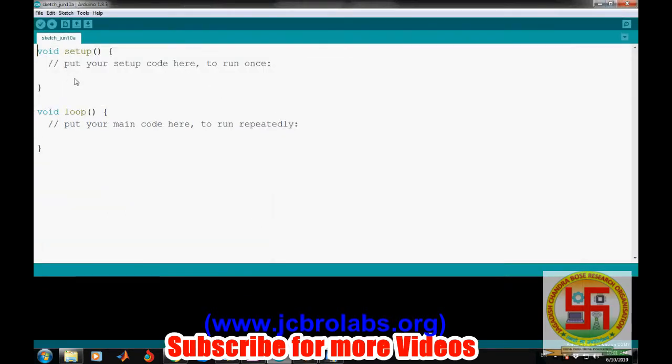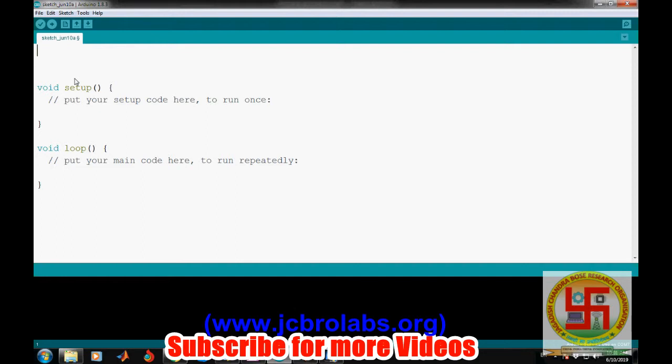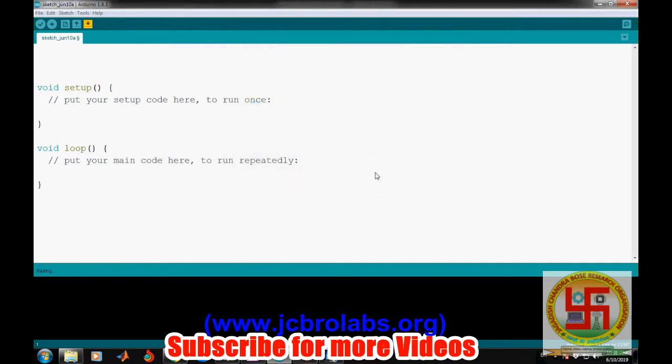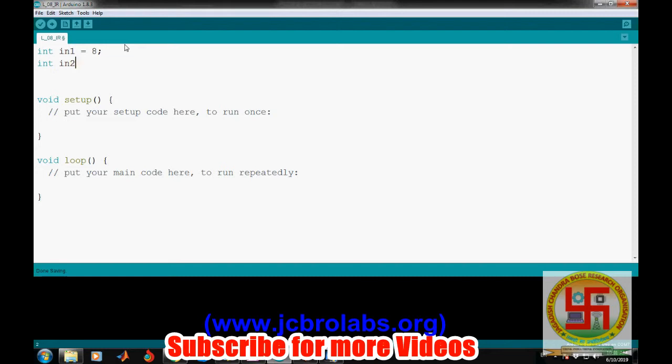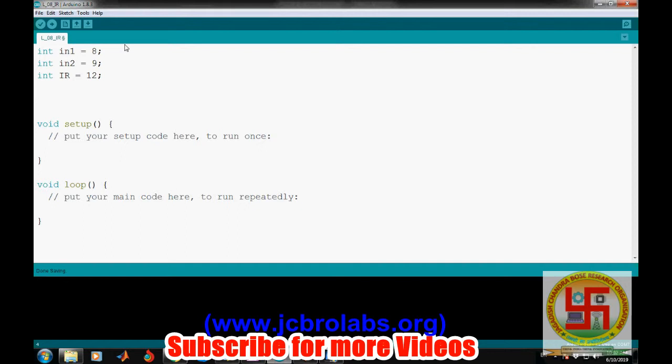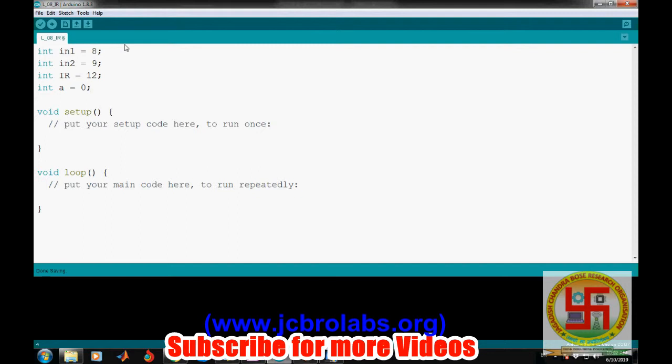Okay. Now let's define the variables. We have two inputs for the DC motor. IN1 is pin number 8, and let's define IN2 as pin number 9, and let's define the IR sensor, which we have connected to pin number 12. And let's define a variable which will be used to store the value of this sensor.